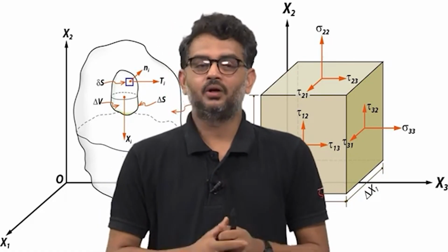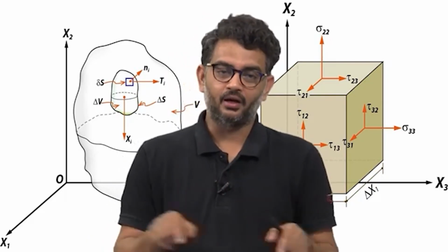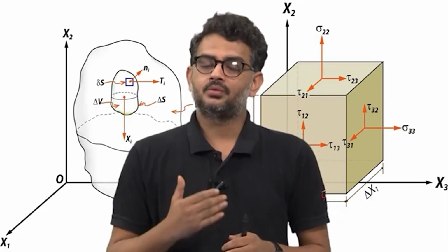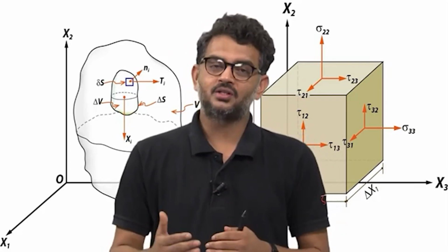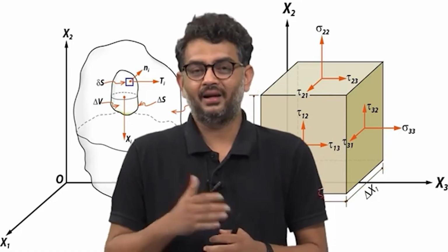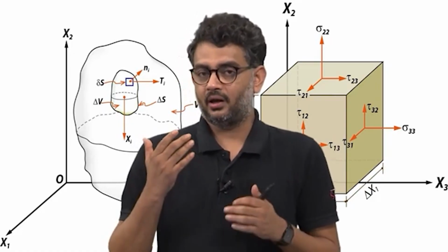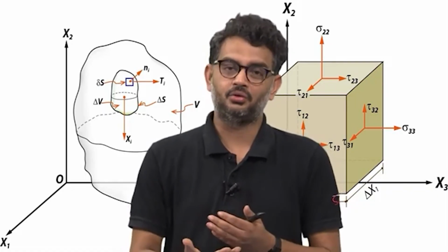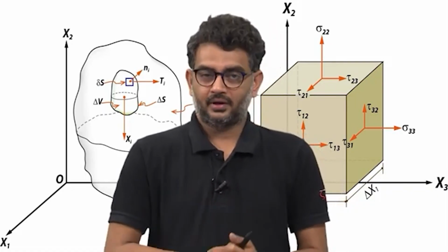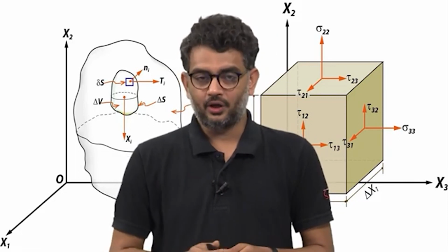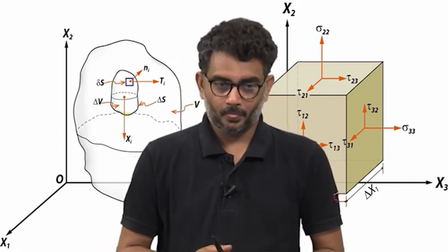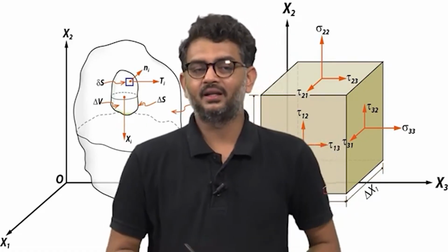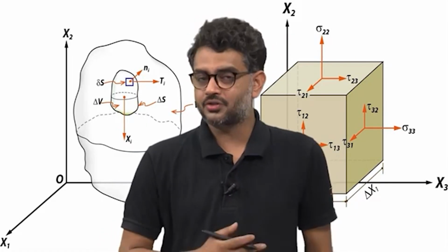Based on the scale you are observing, or your area of interest, you approximate some features and you neglect some features, assuming that these features do not really fit your scale and cannot influence your measurements or your analysis. So this is the concept of continuum mechanics, and we will see that stress and strain as well that we have learned are being studied.